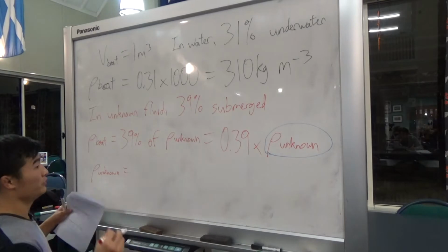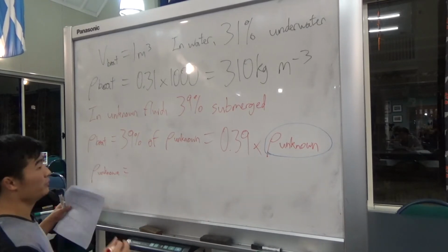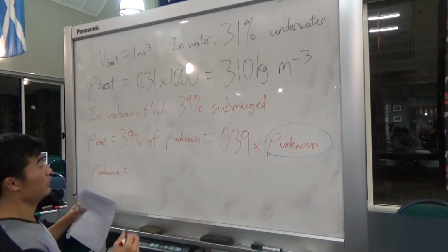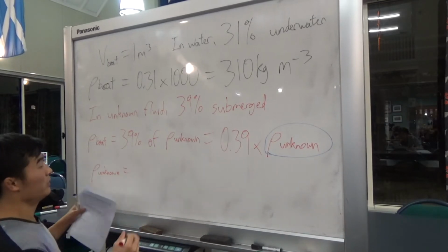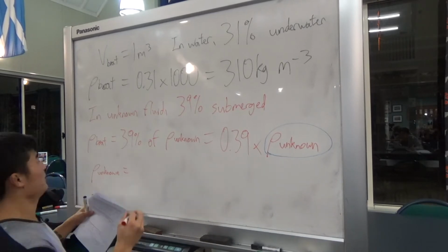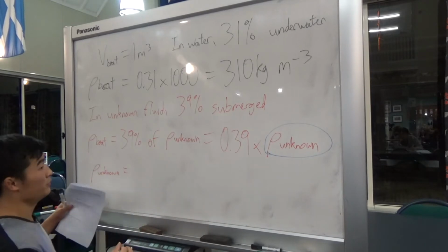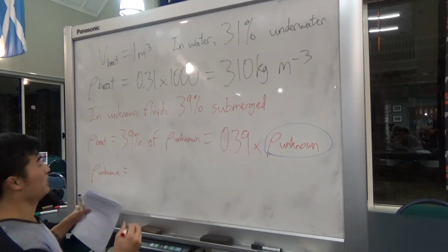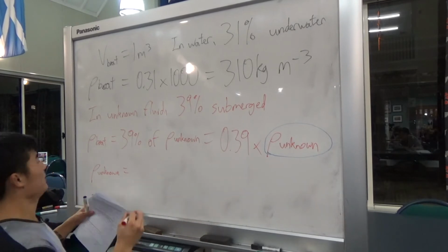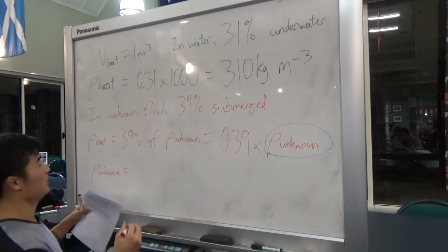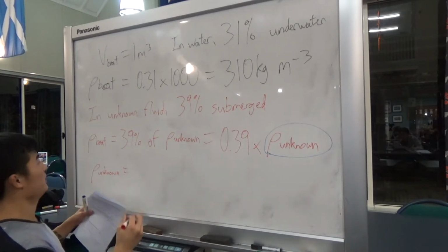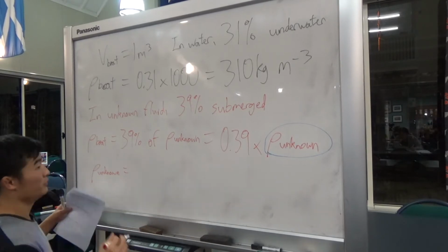So I'll just work that out for you. A1, and the reason that you want to know what the cross-sectional area is, is because the velocity is going to be inversely proportional to the area. So it's going to be going faster when it gets to this narrow point. And if you know that the area has decreased by a factor of 4, then you know that the velocity will increase by a factor of 4.